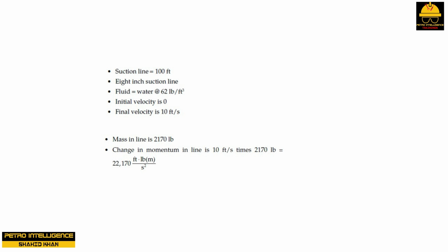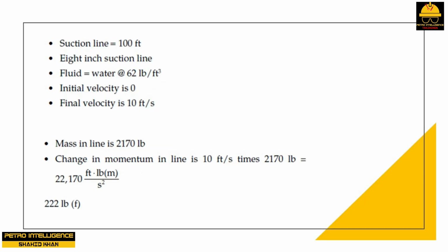If the operator increases the flow rate uniformly over a period of 100 seconds, the change in momentum is 22,170 foot-pounds per square second divided by 100 seconds, which equals 222 foot-pounds mass per square second. 1 pound mass equals 1 pound force times square second per foot. Therefore, the force needed to accelerate the water in the pump suction is 222 pounds force.